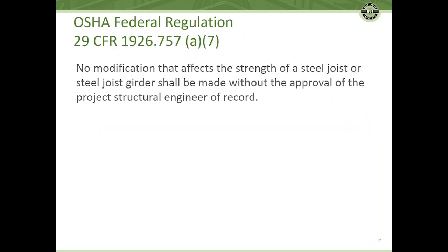With regard to modification of joists, particularly joists that are in the construction phase, which OSHA regulates, there's a provision in their code that says no modification that affects the strength of the joist shall be made without the approval of the project structural engineer of record.